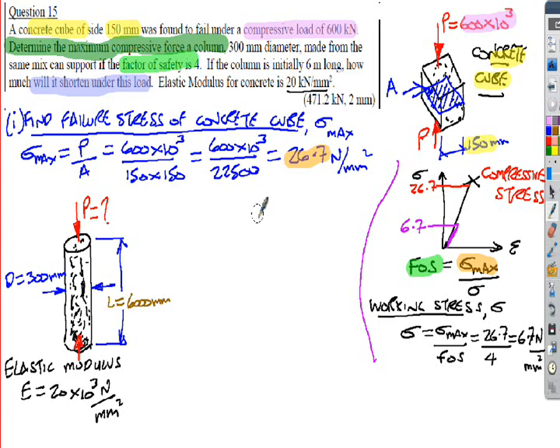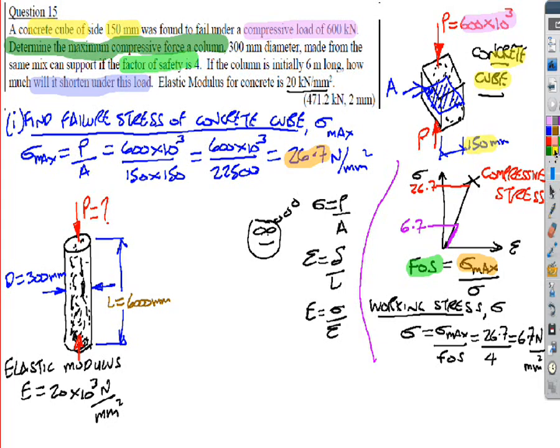I'm going to do my little thinking steps here, so I'm back to my thinking again. So put my three equations down. I've got stress equals the force over the area. I've got the strain is equal to the extension over the original length, and I've got E is equal to the stress over the strain. Just thinking this through. What they asked me to find in this particular question is the force.